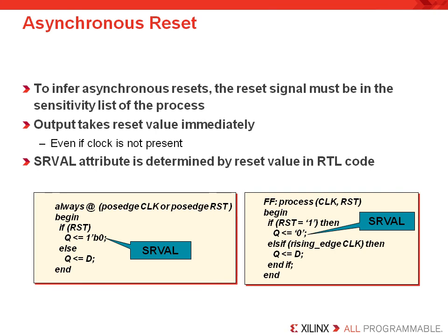Xilinx does not recommend the use of asynchronous resets, even though our devices support them. They simply invite too many designers to design asynchronously, and those designers usually regret that. So in this case, we wanted to point out to you, we have 2 examples of inference of your reset. And of course, since the reset is part of the sensitivity list, that means that process can become active without the actual rising edge of the clock signal.